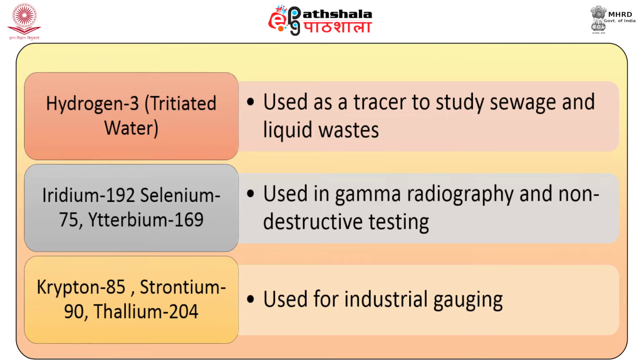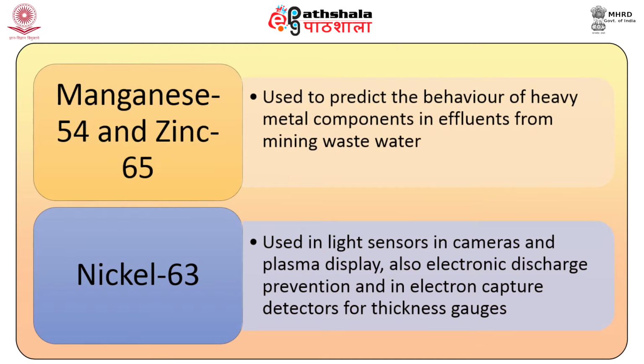Iridium-192, selenium-75, ytterbium-169, used in gamma radiography and non-destructive testing. Krypton-85, strontium-90, thallium-204, used for industrial gauging. Manganese-54, zinc-65, used to predict the behavior of heavy metal components in effluents from mining wastewater.